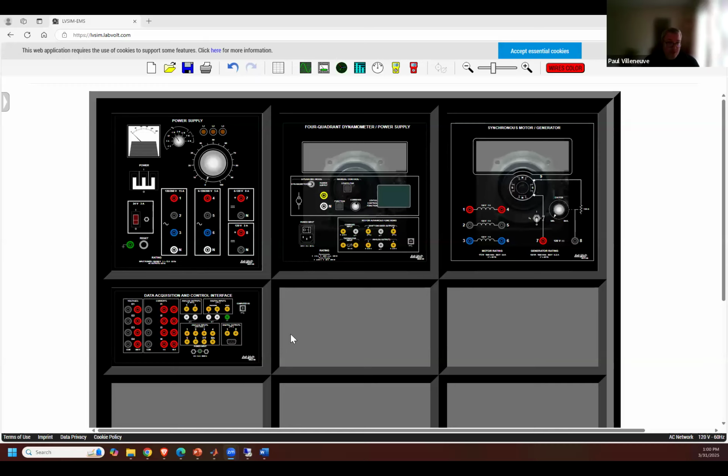And if you think about it, the purpose of a synchronous generator is to convert, not to create, but to convert mechanical power to electric power. That's kind of the important part of it. And how it does it is you have to have a magnetic field, part one. You have to have a magnetic field that is changing, rotating in a closed loop, part two.